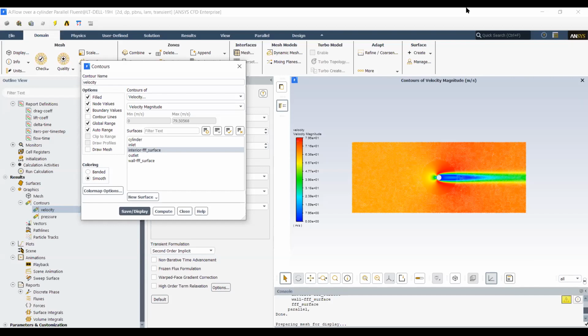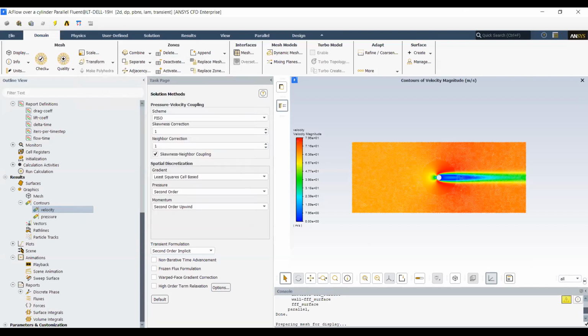So you can do that within Fluent as well, but I did that in another post-processing software that Ansys has to offer, simply because it's a little bit clearer over here, where you could go to animation and collect all the time steps at which you have available solution, and then just simply click the play button to see how the simulation progresses.